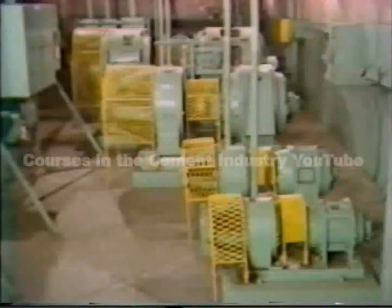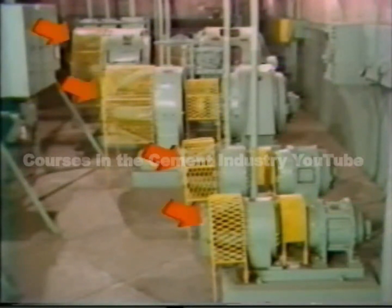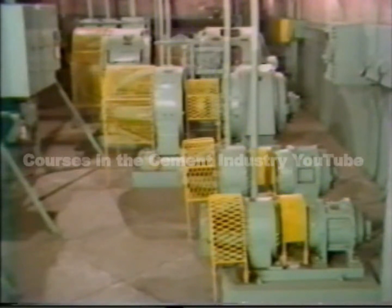Most rotating machines, like these for instance, are made up of two basic parts: a driver component, in this case a motor, and a driven component, in this case the generator. The two components are connected by a coupling. We perform an alignment in order to position the two components so that they rotate smoothly together.